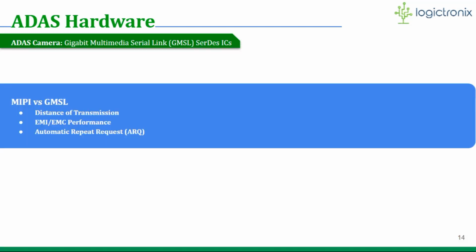Okay, apart from GMSL, there is also another standard which is mostly adopted by camera sensor interface. Okay, that is the MIPI standard. This is predominantly used in mobile devices, as we all know. This standard also provides high resolution, high speed camera interfacing up to 6 Gbps. However, GMSL has lots of merits over MIPI. Okay, let's find out by following points.